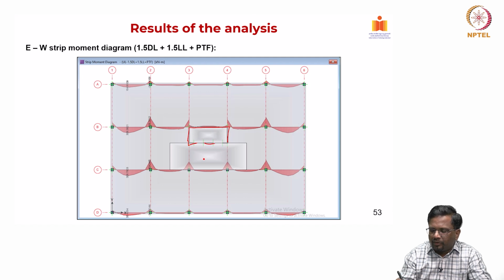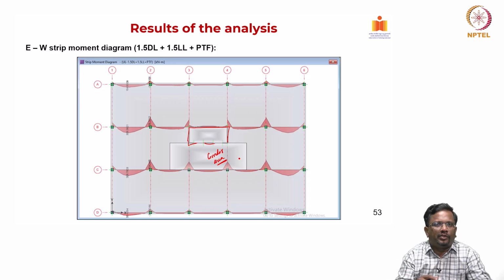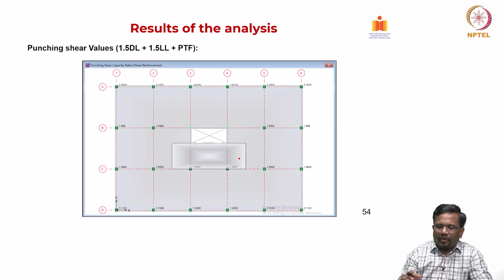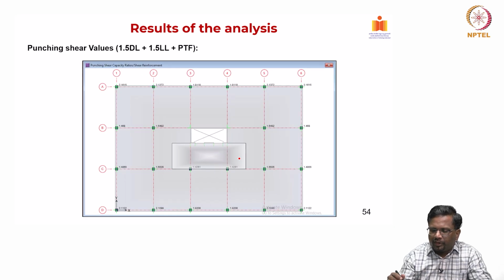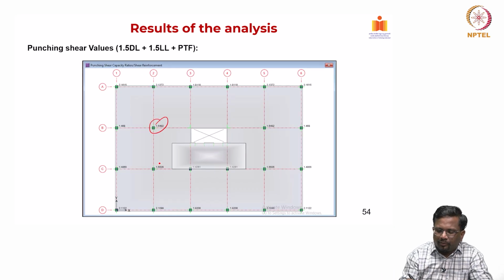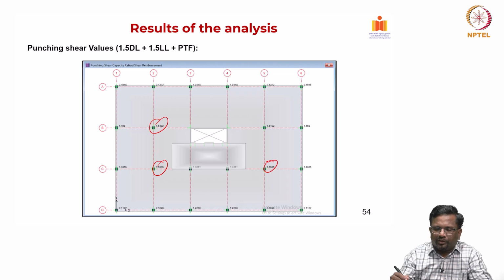In addition to that, there is also corridor area that has slightly higher load, which you have not included in our manual calculations, right. So, now I think these are punching shear. So, you see that for this thing, several locations the punching shear is still failing. This is the punching shear values, right. This is for the factored load.